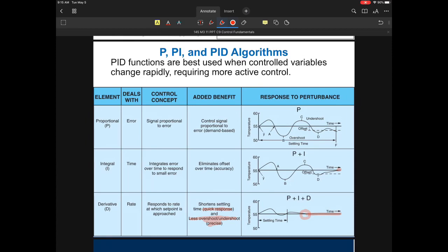In PI control, you'll notice that it took a little bit longer for it to figure it out, and it wasn't until after X amount of time that it figured, okay, now we're good to go. And again, it has to look at all of these factors of how this control is going to do it. What they're trying to do is manipulate or eliminate any type of offset that might build up over a certain amount of time.